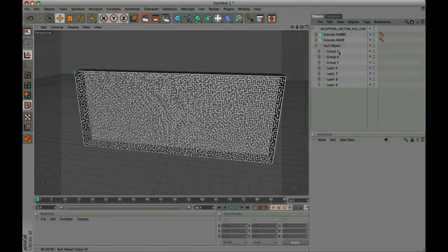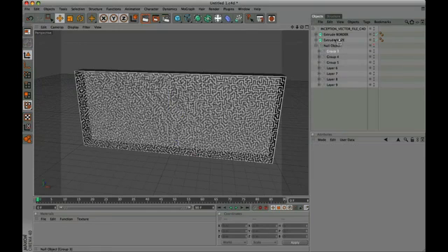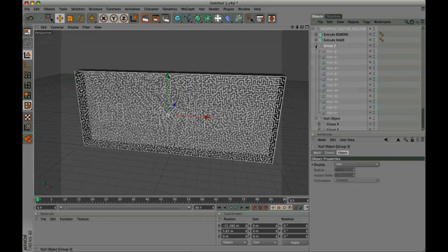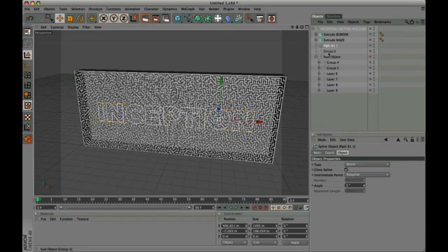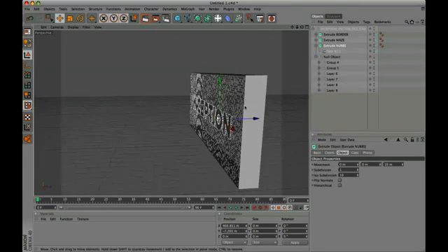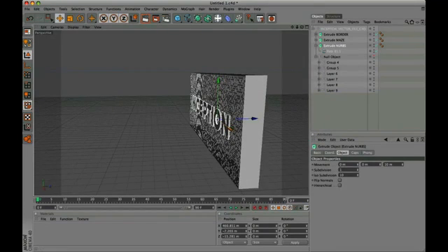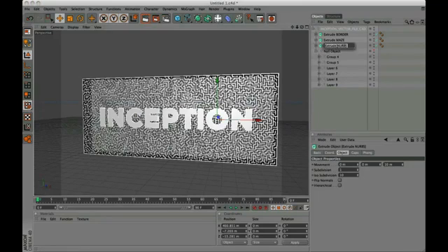We proceed by inserting the logo's mask in the maze. Rename Extrude a Border. Drag out the group 3 layer. Select all the splines and connect. We apply an extrusion with value 10. Drag out of the maze, along the Z-axis. Rename Extrude Logo Outside.